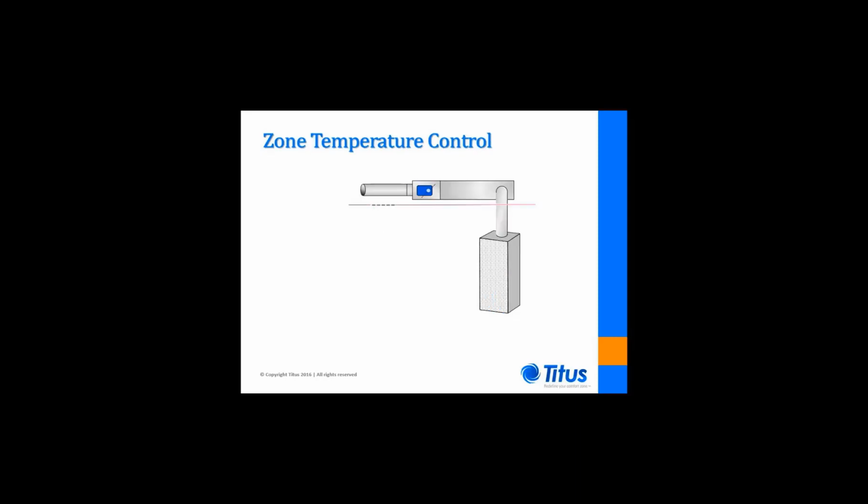A better air quality alternative is to employ a constant temperature, variable volume solution. Supply air is delivered at the intended discharge temperature to a single duct terminal, which then throttles the airflow rate to meet the zone cooling demand, establishing a variable air volume, constant temperature delivery of air to the space. It should be noted that the airflow should only be reduced to a level that still assures that acceptable space humidity levels are maintained. This may necessitate the use of reheat when the zone temperature demand drops below the cooling delivered by the supply air at that reduced airflow rate.